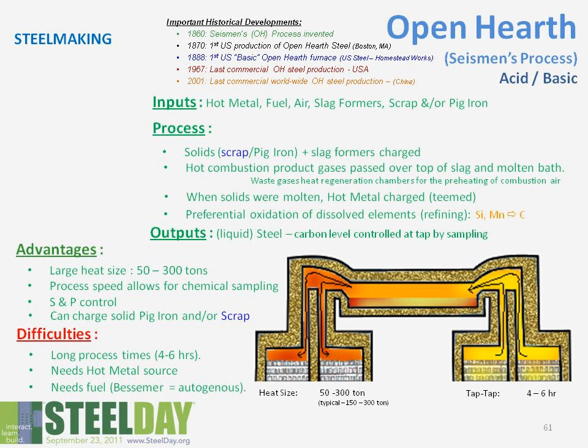Some of the difficulties, though: it was a long process, and it was reliant upon a source of hot metal. The open hearth furnace process basically was obsoleted in the United States in around 1967. Worldwide, the last open hearth stopped operating in China around 2001.